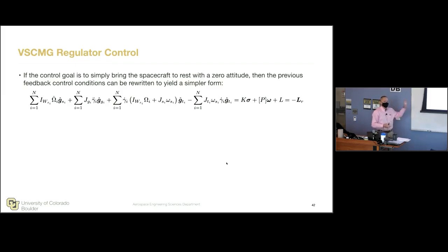If you do the same thing over from scratch just for a regulation problem, then your control is to drive sigma B/N to 0, not B/R, right? Things simplify. I'm showing you the answers if we did a regulation driving everything to rest at the origin, MRP-wise. Then you go through the whole process, and this becomes that control constraint. The right-hand side looks a hell of a lot simpler. I'm doing regulation, so I took advantage that omega transpose, omega tilde, I omega drops out. I'm not feedback compensating for it here. It becomes much simpler. And all of this should be a bold L.